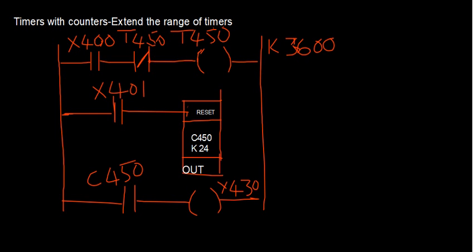So probably you may come across some examples which you have taken in your microprocessors or microcontrollers. Suppose you load a count equal to FF, which is nothing but 255. Depending upon the instruction cycle, for a maximum count you may have a maximum time delay possible.